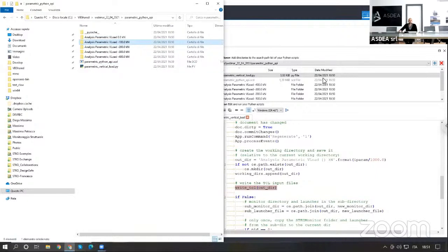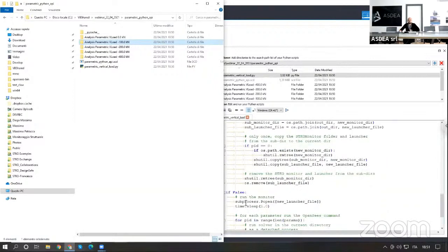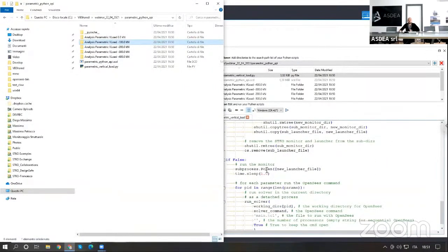Let me see, we have a question on a YouTube channel. Can you change the model using Python while OpenSees is running, or get, read, write results from the analysis when the program is running? Actually, yes. It's not so easy, because you need to understand how the subprocess popen function works. It can be done, but you need some experience with the communication between the processors. I will cover this topic in a future Python API